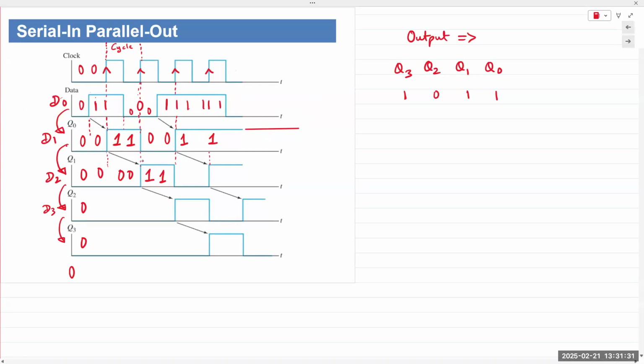And so we get a cascading or a shifting effect. The data keeps on moving down the line. You get the same pattern repeating itself. Okay. We can do this for 8, 16, 32 clock cycles. We're only showing 4 clock cycles here. So 1, 2, 3, 4, because you're only transferring 4 bits of data.